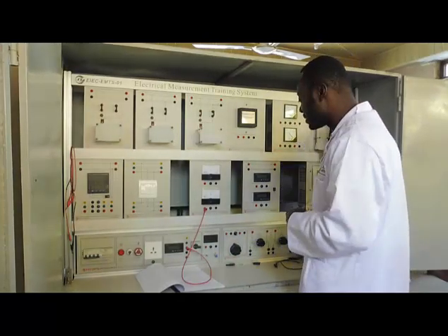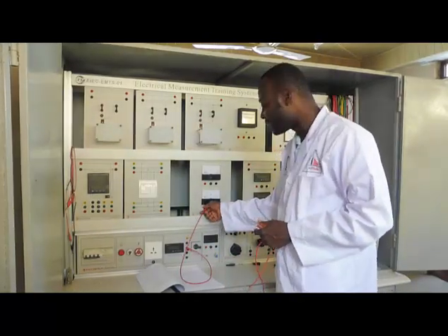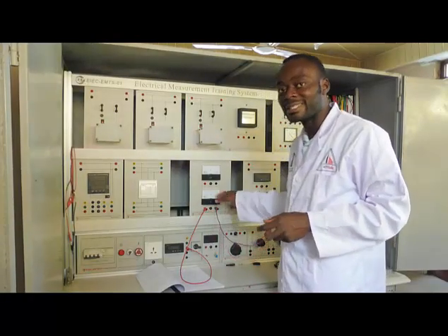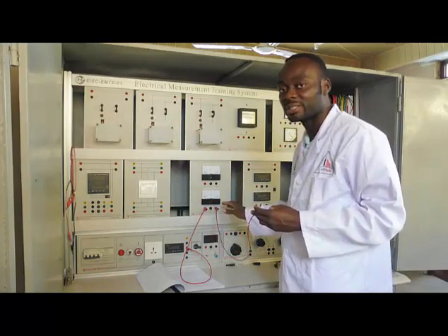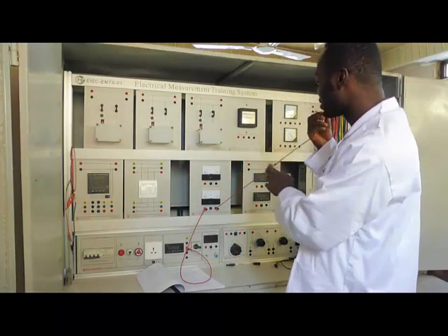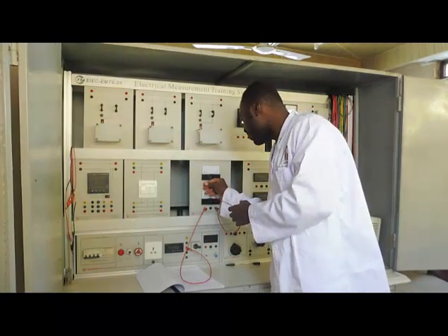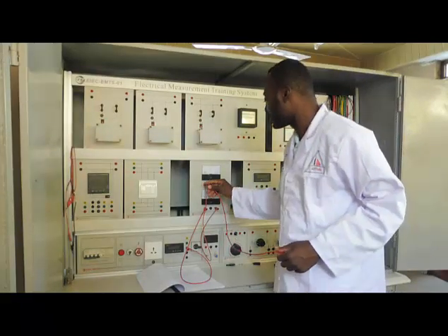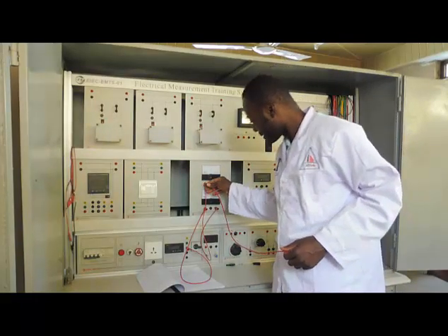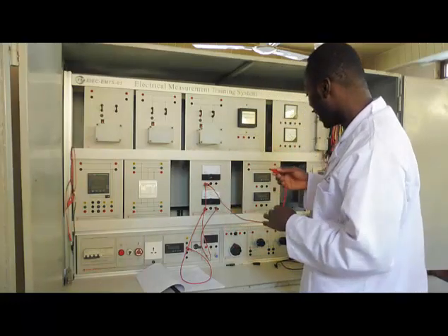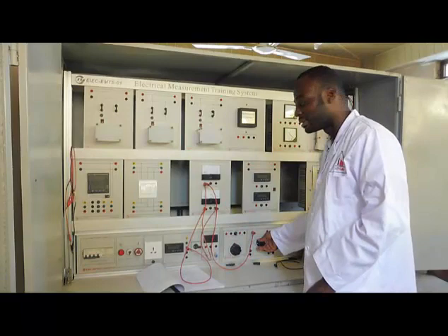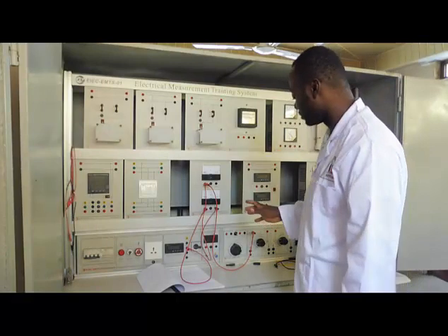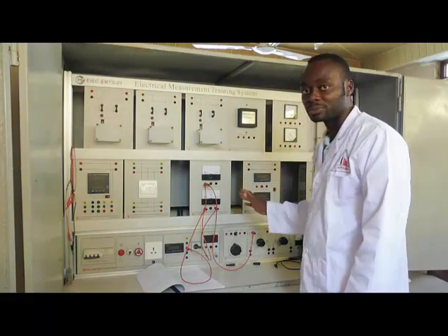So I've input the live cable here. Then I will output what? The live cable, since there's no neutral connection. Then from the output of the ammeter it goes to the voltmeter. Then I will pick from the voltmeter and take it to the adjustable resistor. So when it goes down, I'll be done with the live connection of the analog meter.